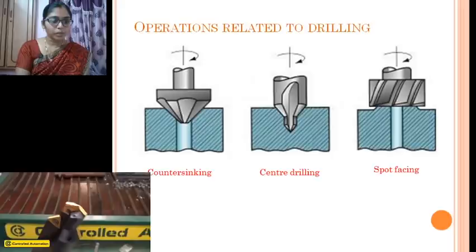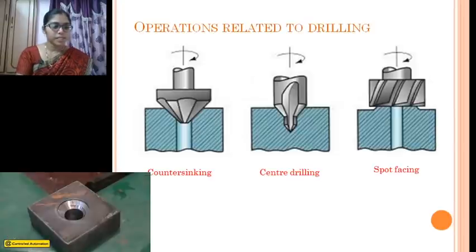Countersinking tool. Right. See here you can see by using that countersinking tool, you can get a tapered finishing on the surface, or tapered up to some depth. We can produce a tapered section.